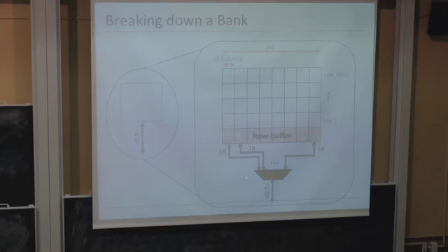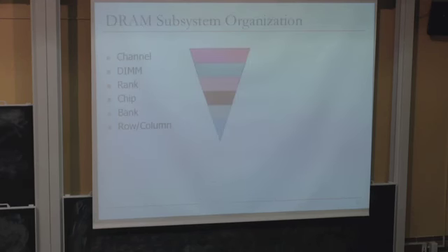So this gives you some realistic values that exist in existing systems. So you could have a chip with 16,000 rows where each row is 2 kilobytes. And each column is a byte. So you can read only 8 bits. Okay? Make sense?